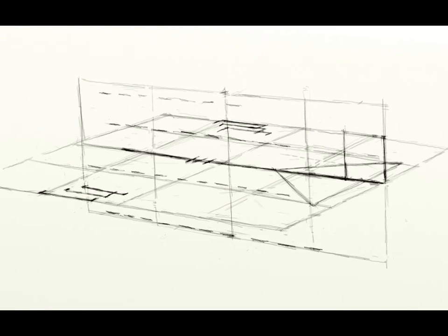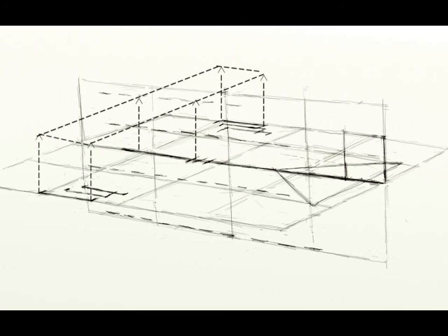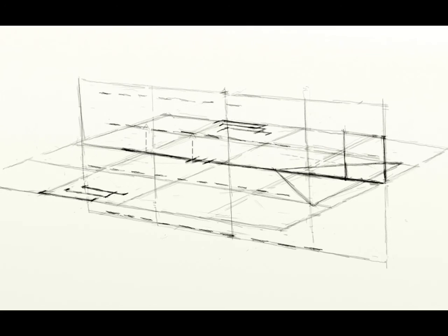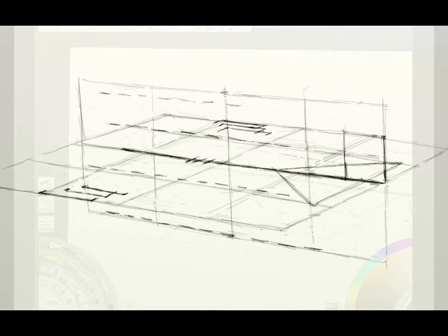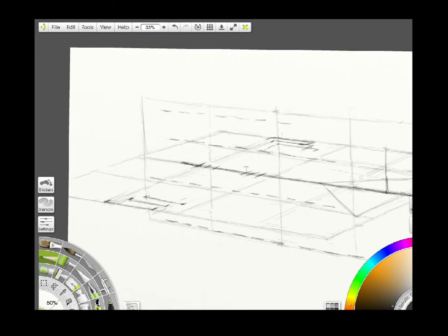Next, we're going to project the wings and tail into position, and let me just show you what I'm going to do before I do the demonstration. We project the top wing up, the mid wing up, and the bottom wing gets projected down below the fuselage scaffold, and then the horizontal stabilizer gets projected up. That's all we're going to do. So I start with the upper wing. I draw some projection lines from the fuselage up to the upper wing reference line.